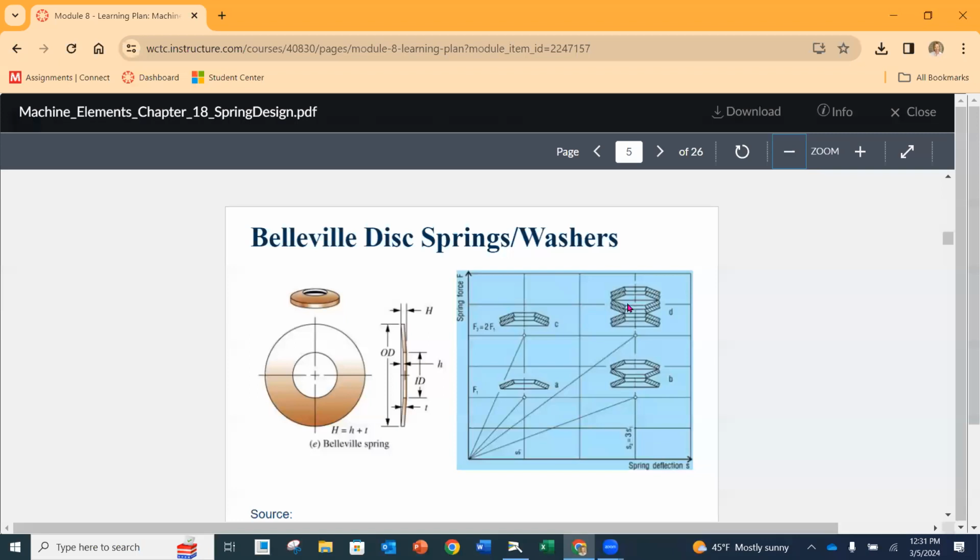You'd have to put them in the tube or... Yep, you either put them in a tube, like you say, or a shaft. A lot of times you'll have a shaft going through and then it'll be inside a bore housing as well. And there'll be some sort of motion in between that you're supporting. They're used a lot with hydraulics and pneumatics as well. So you use the hydraulics or pneumatics to release whatever you're clamping, and then you use the springs to clamp the system or load the system.